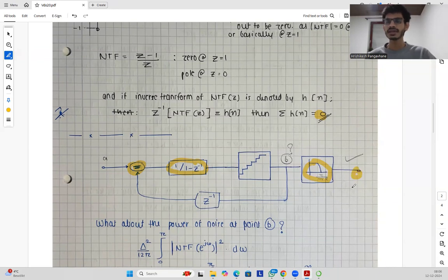This is a technique of showing a lower bit converter to be a very high resolution converter. We have a poor converter, let's say a 2-bit converter, and we are showing it as a higher bit converter using the technique of oversampling, quantization, and noise shaping, and then filtering using a decimation filter.